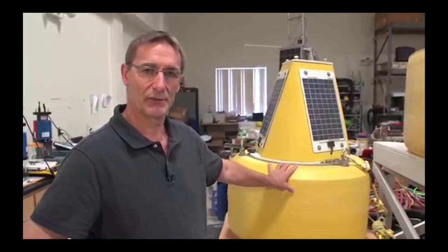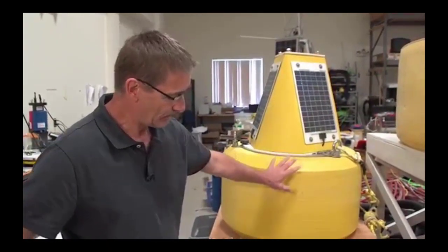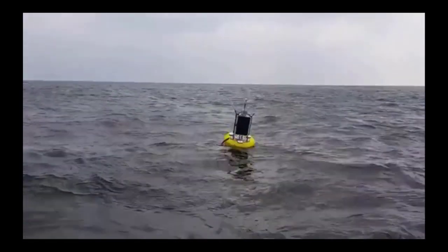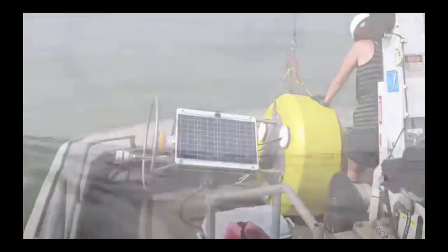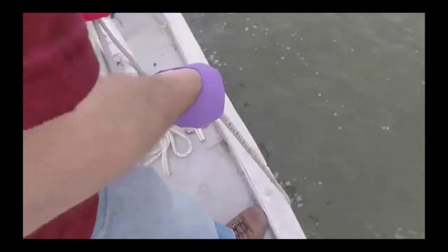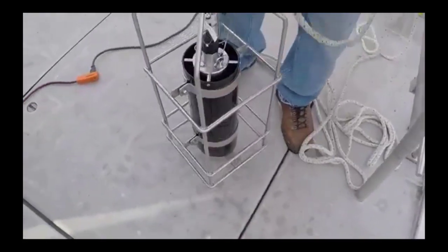We have 4 of these buoys in western Lake Erie, and we have a suite of instruments that are mounted about 1 meter into the water at the bottom of the buoys, and these instruments are able to provide continuous measurements of algal densities and water quality conditions. The instruments are powered by solar panels on the buoy, and then that data is relayed in real time through a cellular modem. Of course, with our sampling, we can only get out once a week, but the instruments basically can produce measurements every minute or 15 minutes and report that continuously. You can see if you're going to have a bloom be advected into your water intake area, for example.